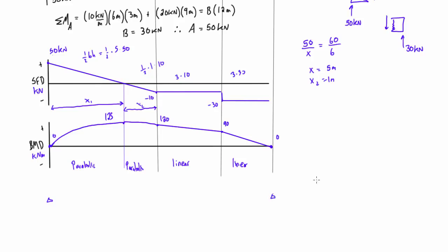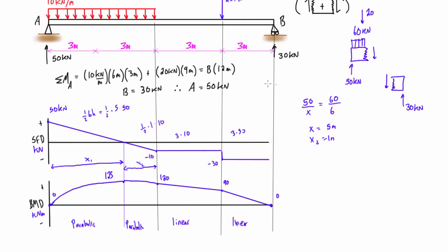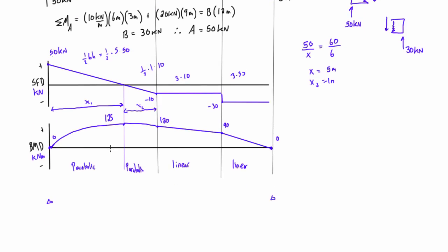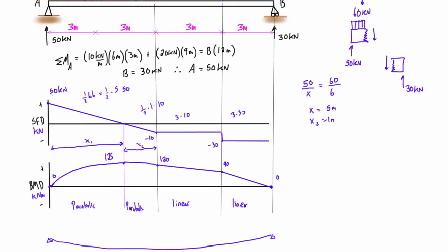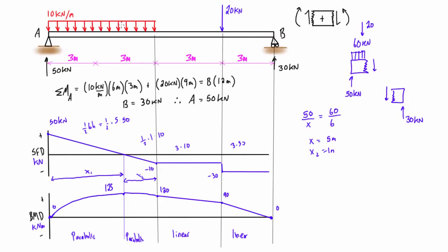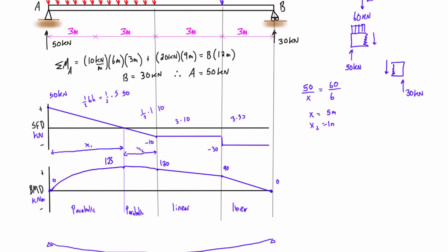So we had a simply supported beam up here, and its deflected shape. Basically, if you're drawing your bending moment diagram, you can kind of eyeball it. It will more or less be like the mirror image of this. So our deflection is basically just going to be more like that. It's just going to sag down. It's probably sagging a little more to the left, but sometimes your teacher will just ask you to draw the general shape, and this would be sufficient to say, yeah, I get that when we load a beam with stuff pressing down on the top like this, it's going to sag down a little bit.